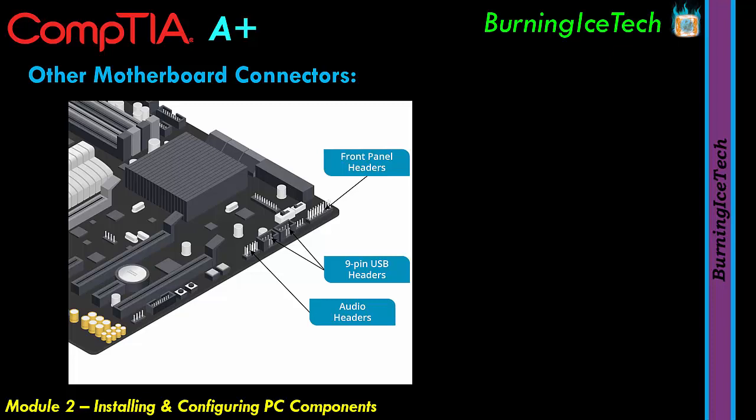So the two blue pins, that's your restart button. If you press the restart button, that's the two blue pins making contact with one another. Those are the only two that you really need to connect: the blue one and the red one. Your restart and your power button. All the other pins are just for little fancy lights in the front of the panel. So when you press the power button, you'll find most computer cases have some sort of light, blue, green, orange, or some sort of fancy lights in the front or on the top of the chassis that's just burning to show your PC's on. So if you don't connect that one, the lights are just not going to come on.